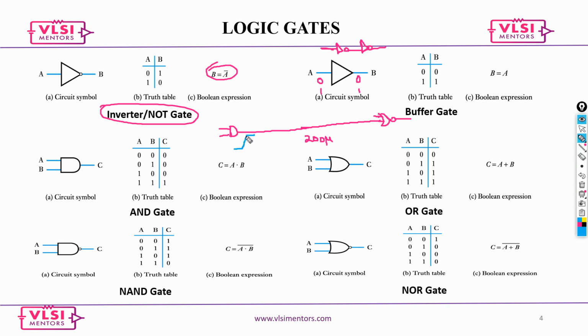It is going to be a strong signal, but when it is passing through this net for a longer distance, there will be R and C, resistance and capacitance. Now when it is passing through all this, the transition at this input pin would get degraded. This is going to be a problem. So you need to restore this transition.